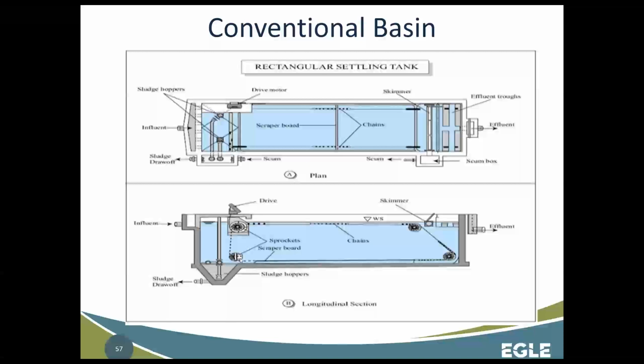I've heard mixed reviews on these scraper systems. Some folks like them. Some folks seem to have more maintenance issues than they'd like, I suppose, is the way to put it. You can think if this blade gets a little crooked or one of the chains starts to stretch a little bit more than the other, it can start to jam up, not function properly, and cause some headaches.